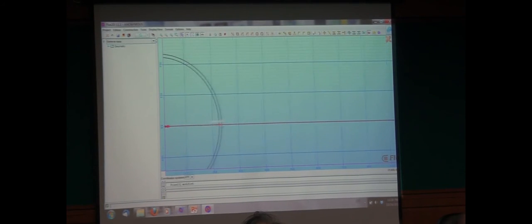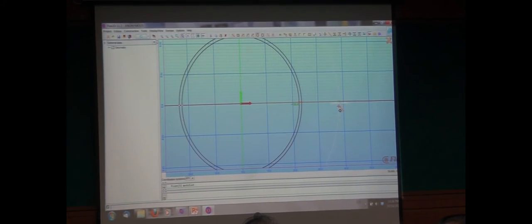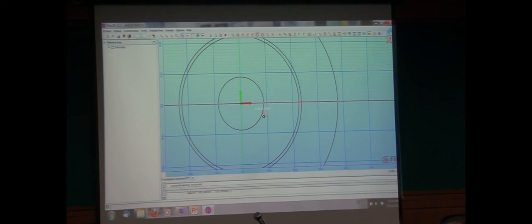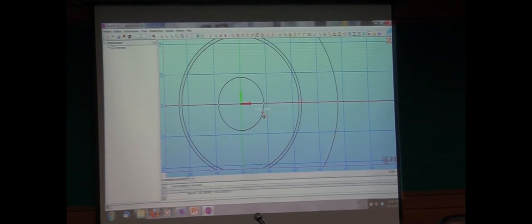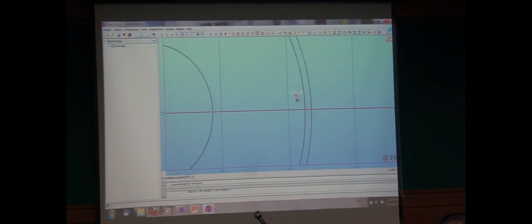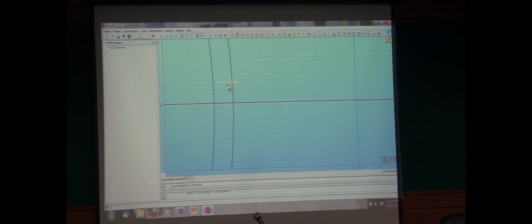So let's go back, and now we're going to enter the outside radius of the stator, so somewhere here, and I'm not going to make it again precise. You've understood by now what I'm trying to do. And then this is the shaft. So I basically have my laminations, my punching, but I don't have the slot. So let's work on the slot. And if I do a slot, I can actually get something. I'll start with a little square here. So that's going to be the slot opening.